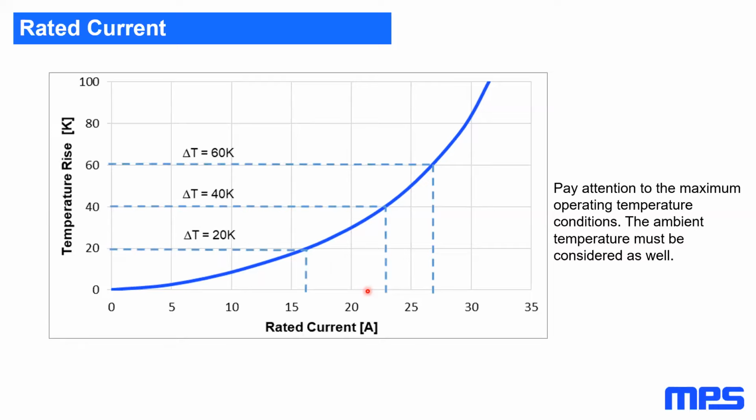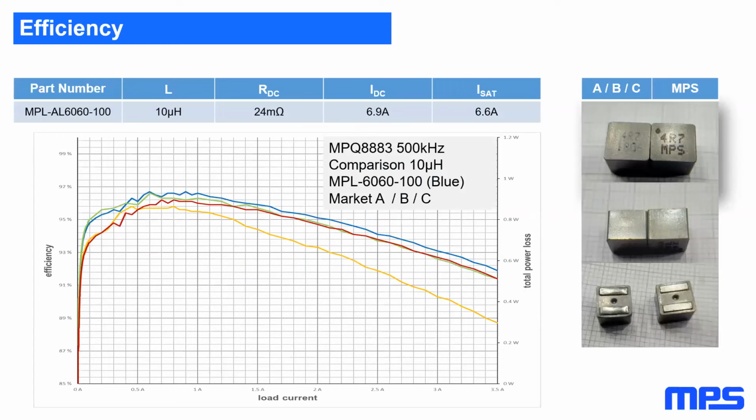Great. Let's see, for the efficiency curve, it says 500 kilohertz. This curve will change with switching frequency. How do we account for that? Yes, as you can see here, the whole chart is measured at 400 kilohertz. What is changing here is the current. But the permeability is frequency dependent. And all core materials, what we have in the market, are frequency dependent, so there is no other way. They are driven by the frequency and the losses are increasing with the frequency.